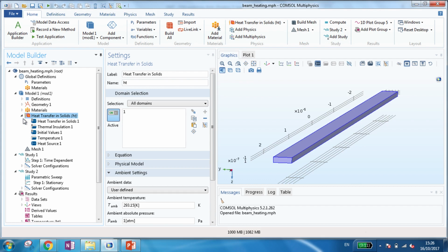Laser light has a Gaussian distribution over the beam, and we know the power, we know the thermal absorption, and then we can calculate the thermal transfer. So my goal is to have a Gaussian profile.